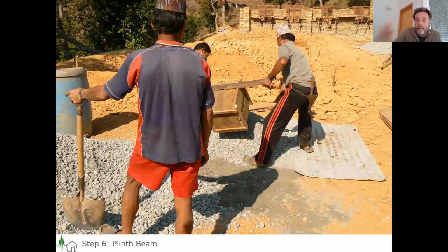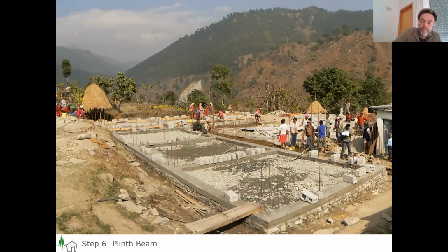All right. Then I always made sure that the measuring boxes were there, so that we are always mixing 1:2:4. That means for concrete, one bag of cement, 2 boxes of good quality sand, 4 boxes of good quality stones, and the mix should always be correct.